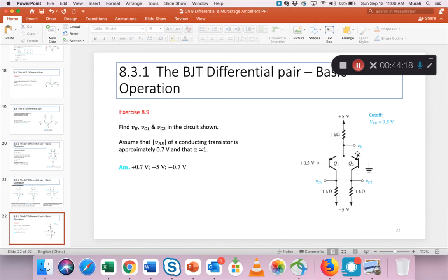Because this is grounded, VEB will be greater than 0.5 and it will start to conduct. So the point is, the way this arrangement works, one of the devices will be automatically pushed into conducting or the active stage, and the other automatically becomes cut off because its emitter base junction for the same applied voltage will be pushed into reverse bias.